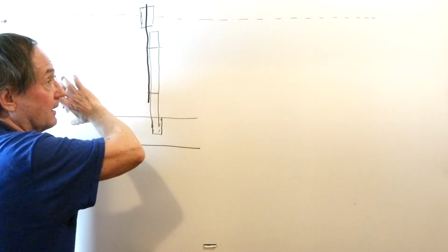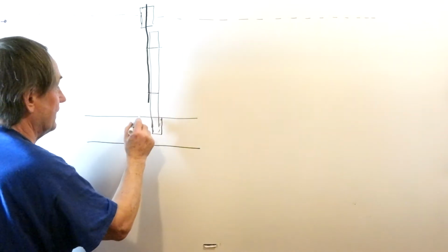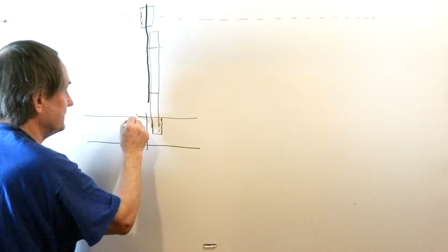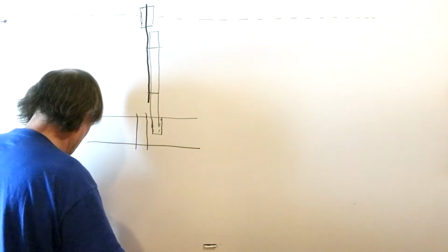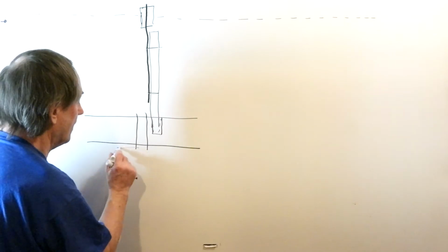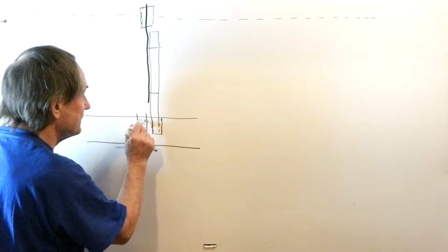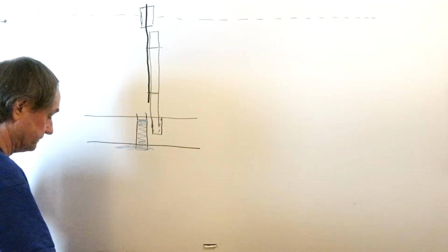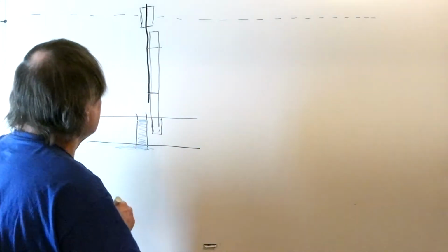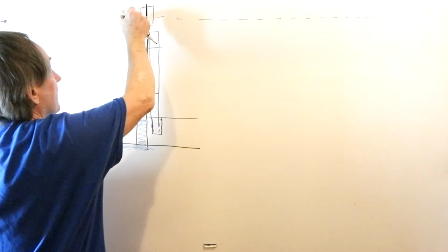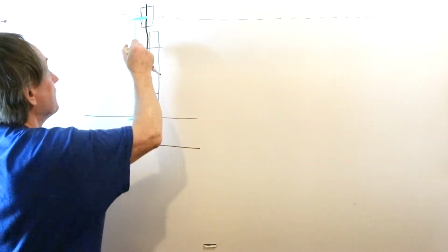Then, on the day of making measurements, once all the targets are lined up with a tangent, we bore a hole through the ice and let the water level come up. Say we have our water underneath the ice, and it comes up to within a couple inches of the surface of the ice. Then we measure the drop distance, the distance from the center of the target to the surface of the water, and record that height.